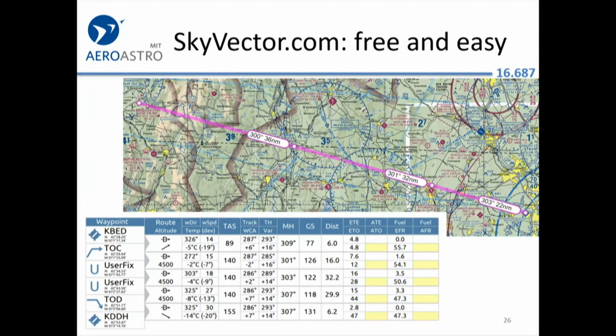So you steer that for a while, see how it goes. It's supposed to take you about 12 minutes from the time you took off to the time you reach that point, and you write down what actually happened. And if you see the airport, well, let's see, it's supposed to be on our left. If you see the airport on your right, you say, well, the wind's not quite what I thought. I'm going to steer 10 degrees right. And then that river crossing, I guess, isn't really ideal for heading correction. You probably want to find some other landmarks as well.